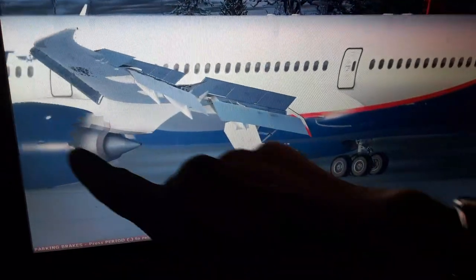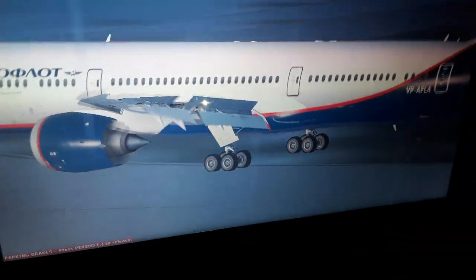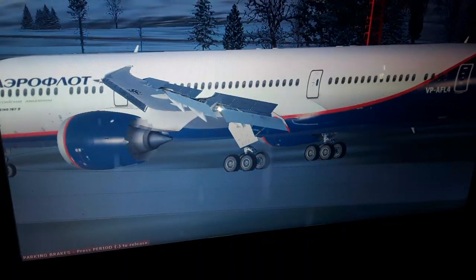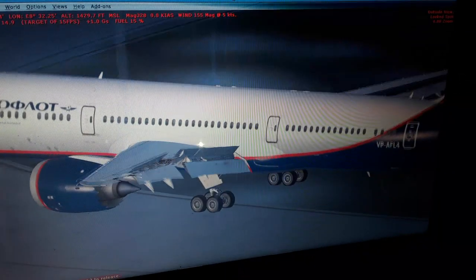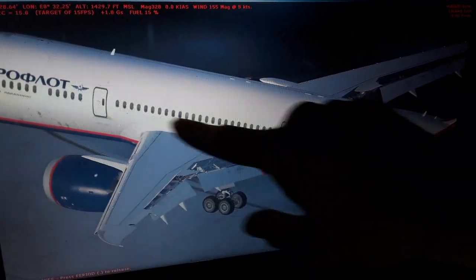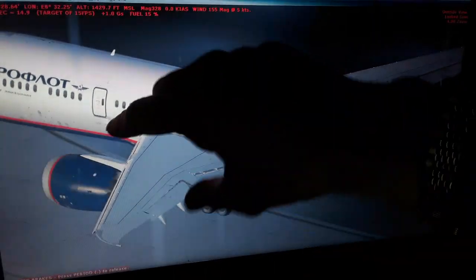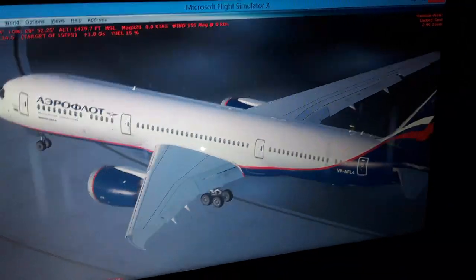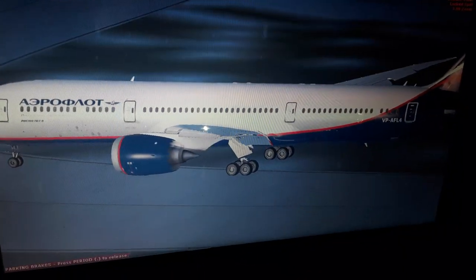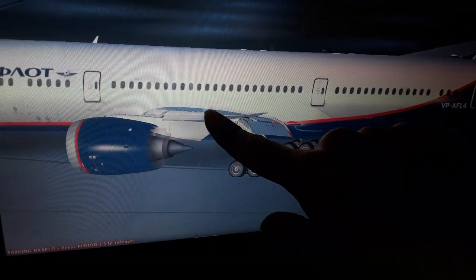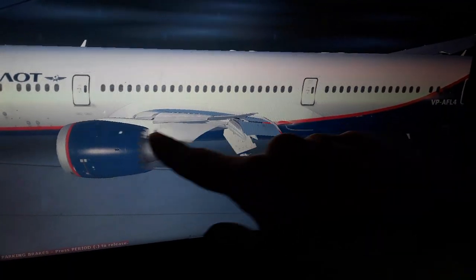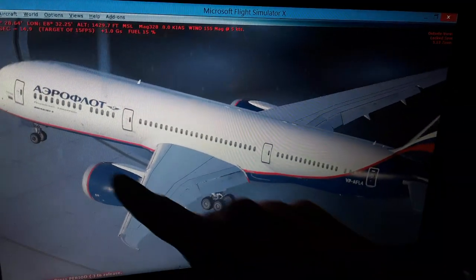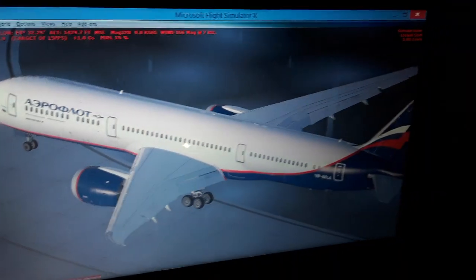jet blast over here from the exhaust cone, and we have high pressure below the wings, the airflow moving slower below the wings, which pushes the aircraft weight and wings up into the air. We have higher airspeed above the wings, which sucks the aircraft's weight and wings up into the air, the aerodynamic lift. Also, you can see we have the fuel lines for the engines. We have the fuel lines inside here from the fuel booster pumps and the low and high pressure fuel valves. We have also the wing and engine anti-ice over here, with hot air from the engines coming in from the manifold.